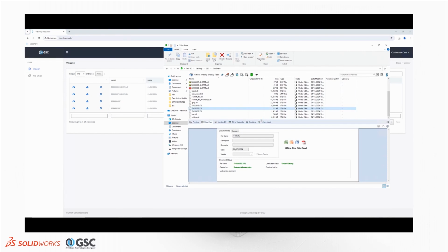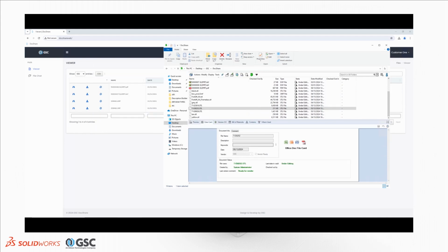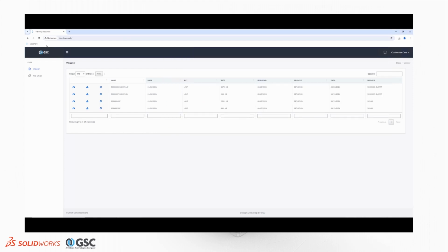To share a file from PDM, the user utilizes data card fields to select the group or groups to share to, and check a box to mark the file as shared. Any shared files are still stored in PDM, but made visible to outside groups. Once a file is marked as shared, it will appear for the shared group once they have logged into their DocShare account.